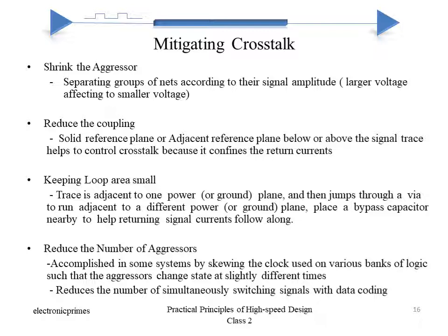And you try to reduce the number of simultaneous switching signals with data coding. So with these few guidelines, we can try to mitigate the crosstalk.